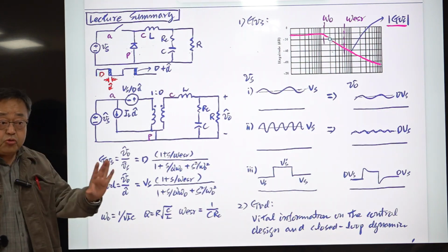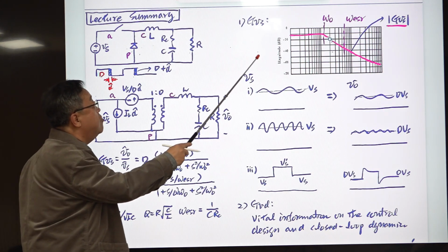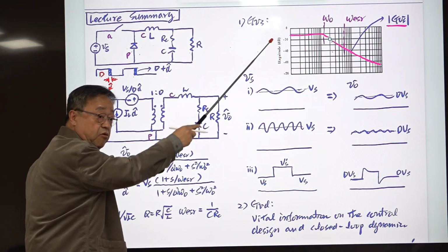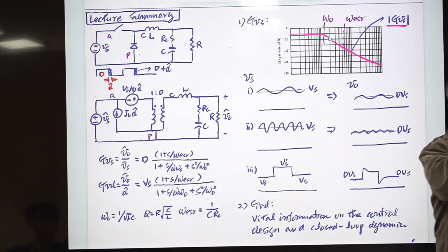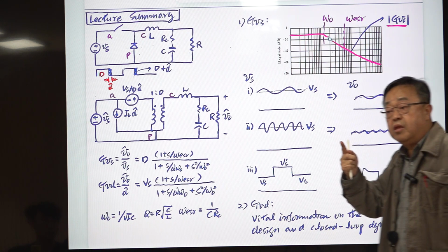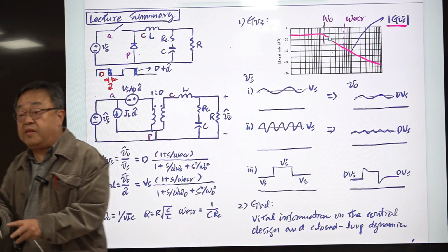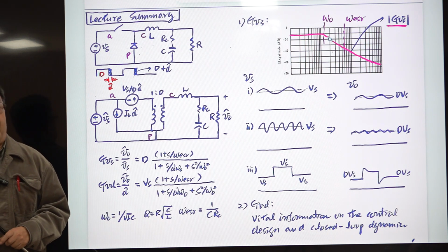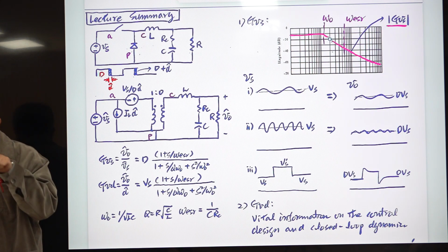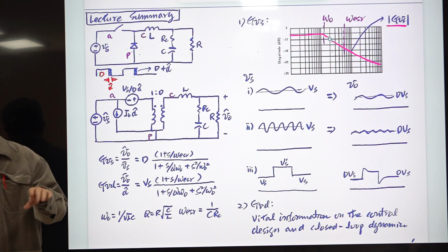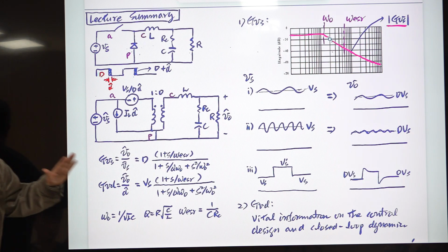Okay. Suppose you applied some arbitrary waveforms, some triangular type periodic waveforms. Then that periodic waveform can be decomposed into sinusoid components with many frequencies: fundamental frequency and higher order harmonics. Okay. Then you use superposition. Consider one component and another component and so on, and add them all together. Then you have complete knowledge about the output due to that periodic signal, which is a non-sinusoidal waveform. Okay? Because of that, you have the entire information about this in steady state and transient response.